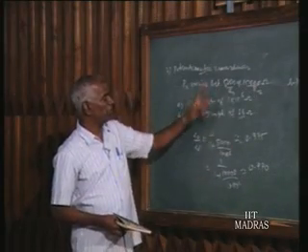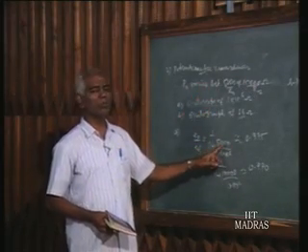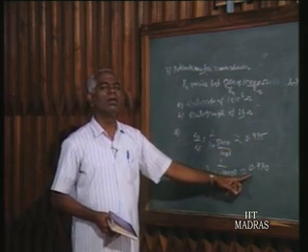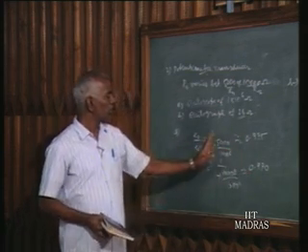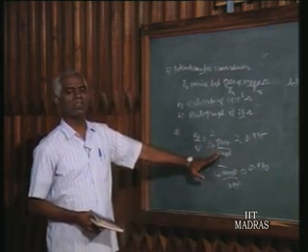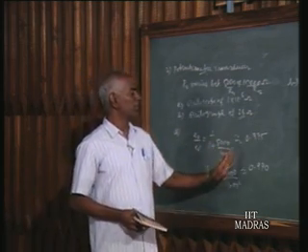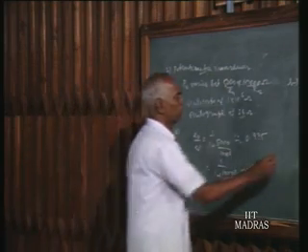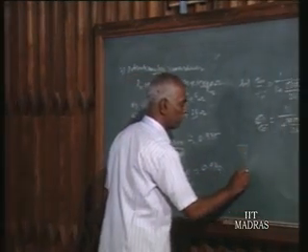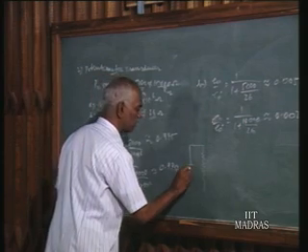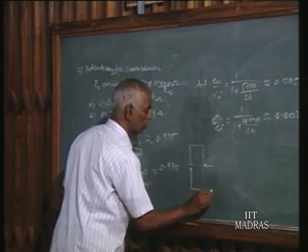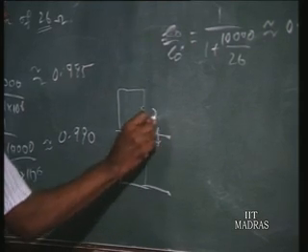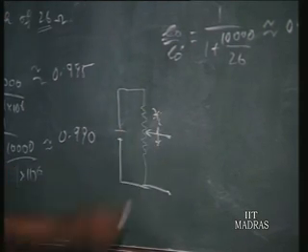When we connect a very high input impedance to this varying output voltage, then this varying effect is not found in the output of the high resistance device. That is what you have learned. So we draw this again: the potentiometer transducer with its excitation voltage. These are your output terminals. This is our xi, the input distance, and we have got the output voltage.